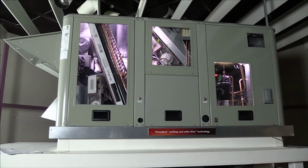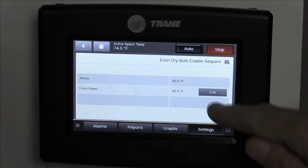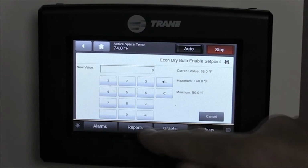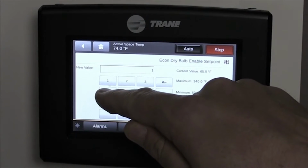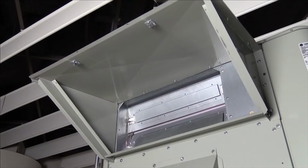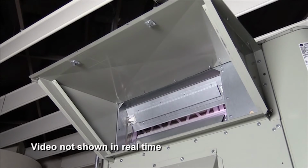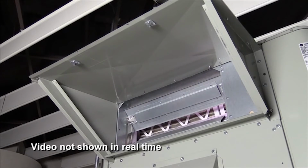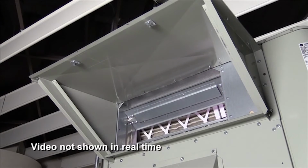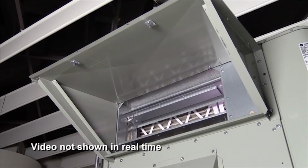Now, the first step of the acceptance test is to enable the economizer and simulate cooling demand. So we use the controller to change the high limit shutoff set point. I changed it to 140 degrees, which forced the economizer to be enabled, since the outdoor temperature is always below this limit. Then we watched as the unit responded. The outdoor damper moved to 100% wide open, while the return damper fully closed. This confirmed that the unit was indeed economizing and trying to provide all the cooling with outdoor air.